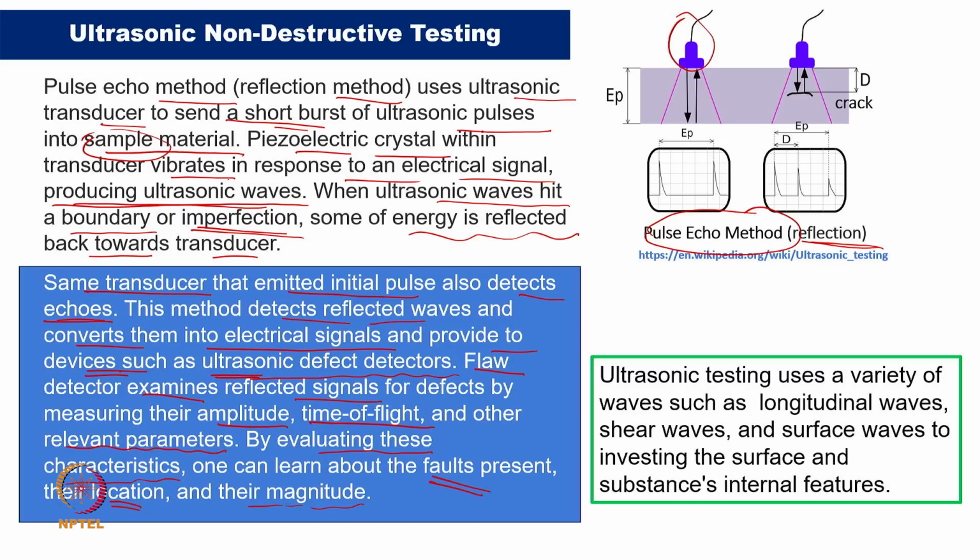How much we get depends, because even a little bit of change in the surface roughness can spoil the complete thing. Even though I am saying we do not really make a sample, we make surfaces which need to be examined, and they need to be clean. If the surface has some sort of corrosion or rusting, I can't use the sensor directly. So, preparation of the surface is important, not the preparation of the sample which we do in destructive testing. Please do not get confused, here we also prepare and clean, so that sensors can be attached to the surface properly.